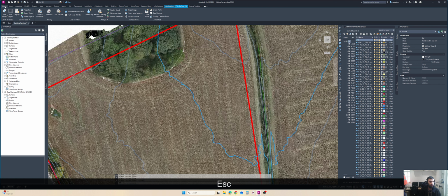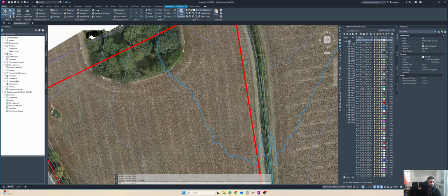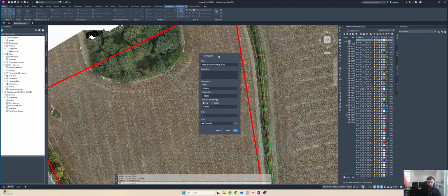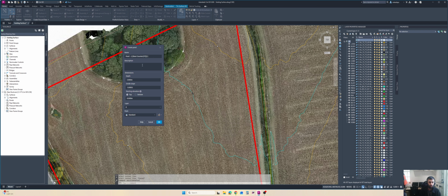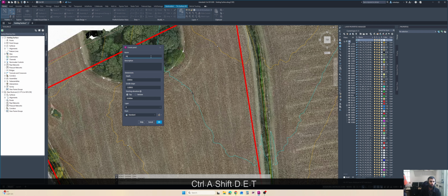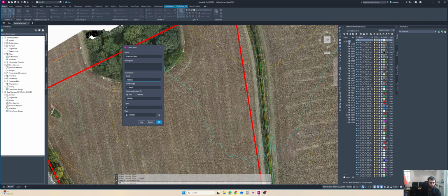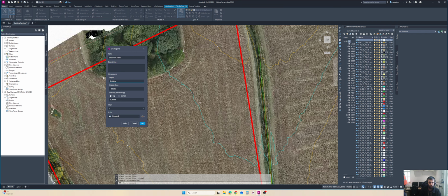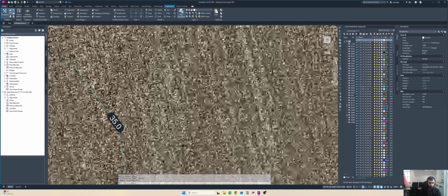Okay, so it was in the pond. We click on the pond and then create a pond. So this comes up with this dialog box. So pond, I can say like detention pond, and the depth will be like 2 meters. Inside slope is okay, and then starting elevation from the top, and that elevation is, if I can quickly zoom in, I think it was 35.